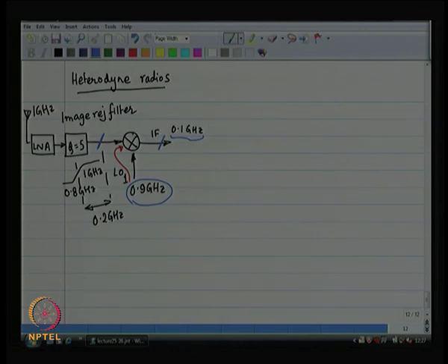So, large Qs are very difficult to get. So, you make something with a small Q, which means that you need your IF to be a significant fraction, maybe 1/10 of your RF. Now, that is probably no good, because if I want to put my A to D converter, my low pass filter, then this is no good. I can't do A to D conversion at 100 megahertz, it is very hard. I would rather do it at 10 kilohertz or 100 kilohertz, not at 100 megahertz.